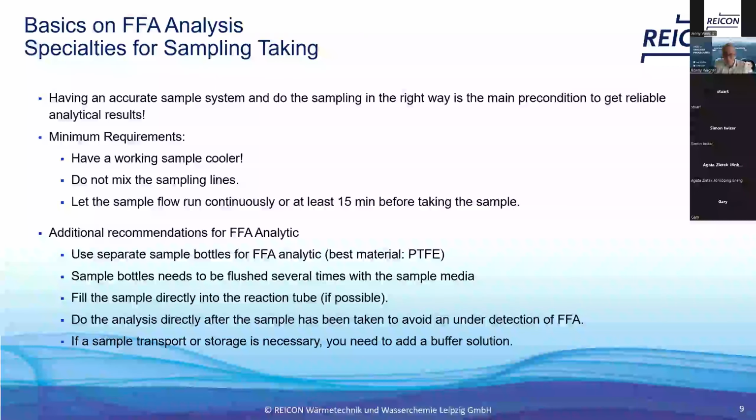As the name says, it's a film-forming product, or film-forming amine. So it will create a film everywhere, also on the sample bottle. It's really important that you use separate bottles for the FFA analytic, and best is a separate bottle for every sample point.